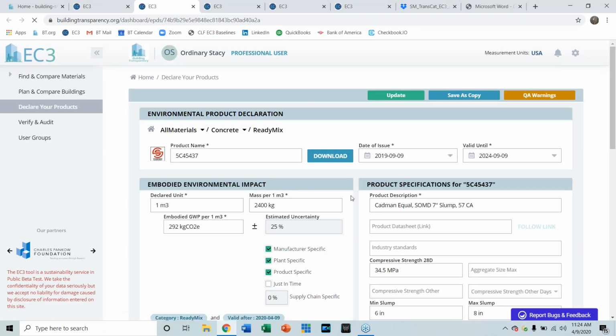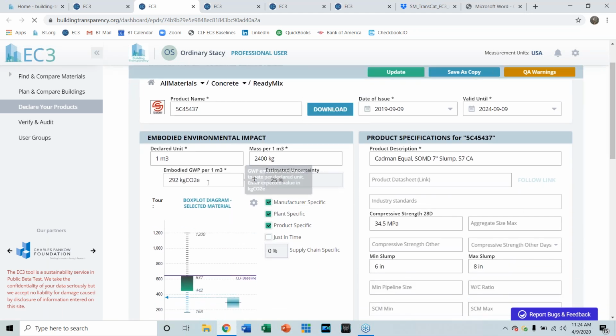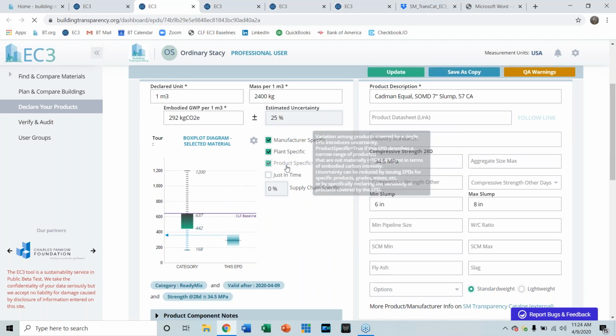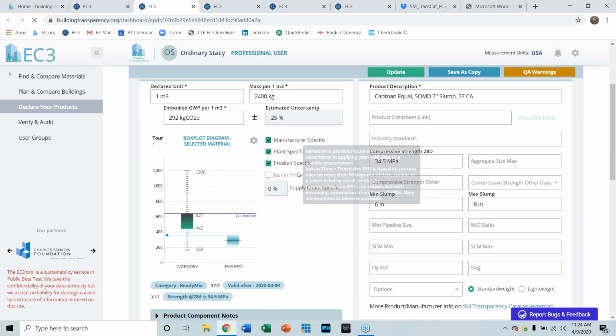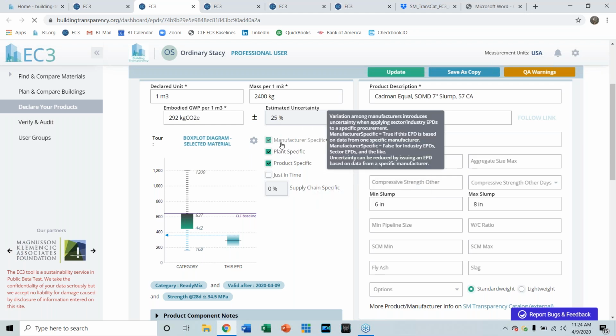You can go to the digital version of the EPD. So again, this is us taking what are typically PDFs and creating a digital version where we've created fields and put in all the information that we could pull out, including things like the expiration dates, but also assess the EPD for certain things. And these are 4 categories that were set up based on metadata, which is something that came out of Sweden for assessment and comparability of EPDs, but also something that the Carbon Leadership Forum then fine-tuned as part of our process last year.